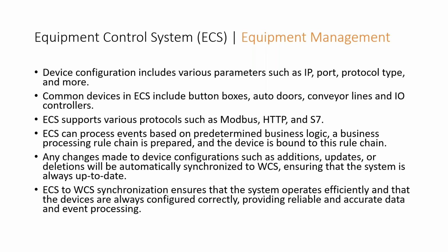Common devices that ECS interfaces to are button boxes, automatic doors, conveyor lines, I/O controllers, traffic controllers, these kinds of things. Like it says, we do support multiple protocols. We support Modbus, HTTP, S7 for Siemens, MQTT, OPC UA.